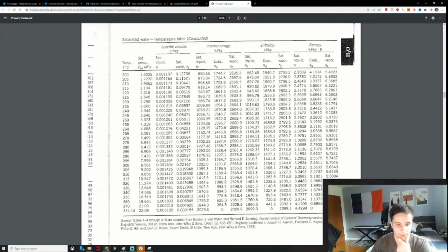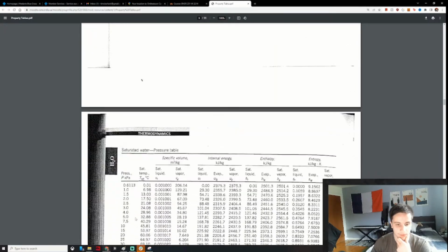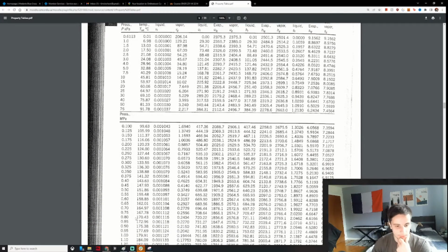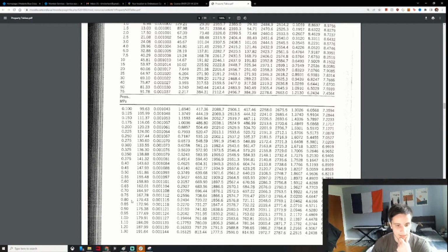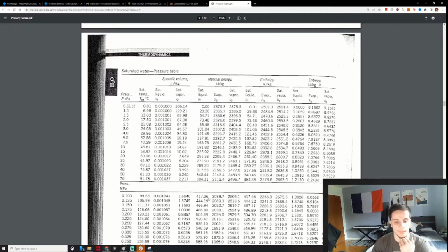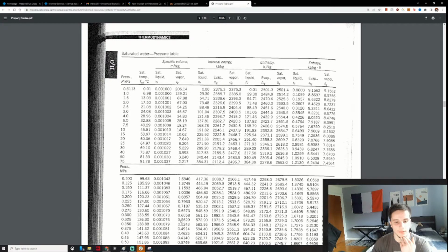We don't have temperature at 400 Celsius, so let's check, maybe do we have 800 kilopascal, which we should. So 0.8 megapascal has a temperature of 173.43 Celsius, not 400 Celsius. So we know, since these two don't match up with what the exercise tells us, that state 1 is not in the saturated water or the mixture phase as a saturated vapor.